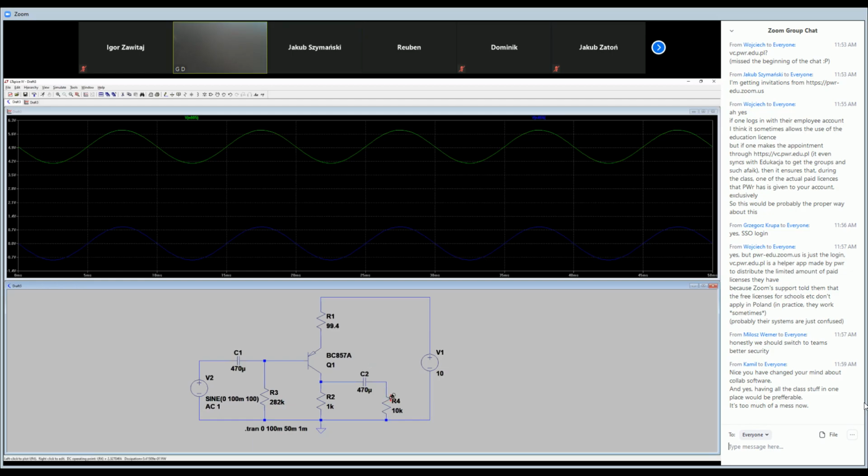Into the load. It depends what will be the input signal. This is one thing, because the power is delivered in the form of the AC signal. That's right. And the second limitation is the maximum current of the collector and emitter for the transistor. So you have to check on the data sheet for this transistor what is the maximum current which can pass through this transistor. That's the limitation here.